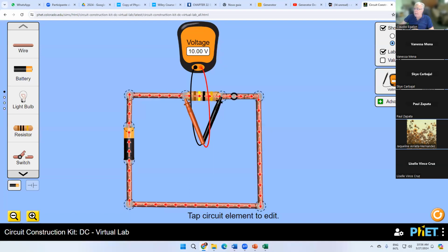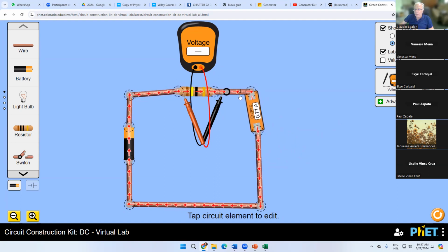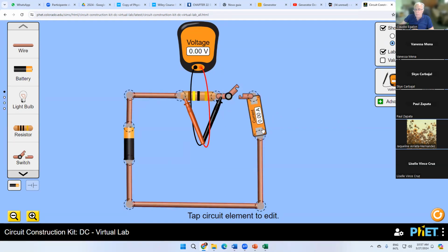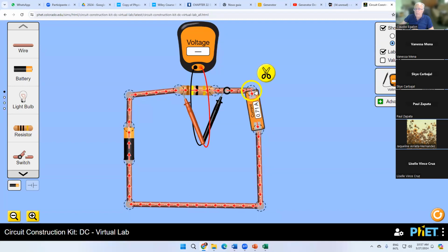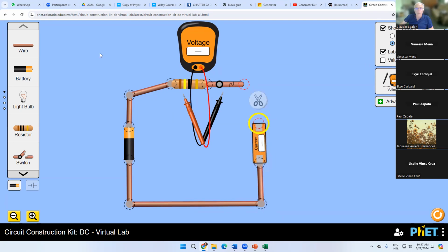That's what we did in lab number 4, right? If you want to find out the current in the circuit, we have to connect the ammeter in series. Okay, I have to break the circuit, connect it here, and okay. I don't like it because it's crooked here, but let's see. Let me break it. Okay, now I can get it straight. Okay, straight. More wires.